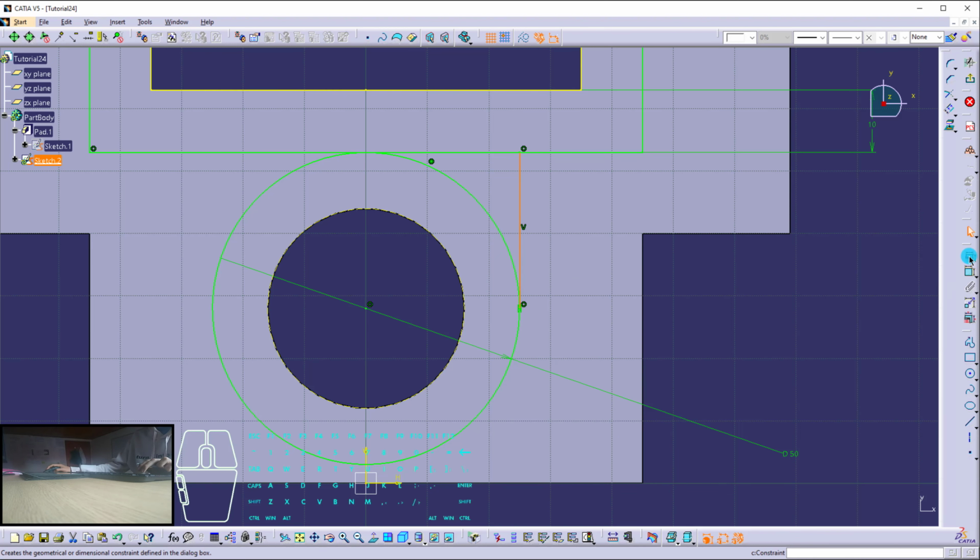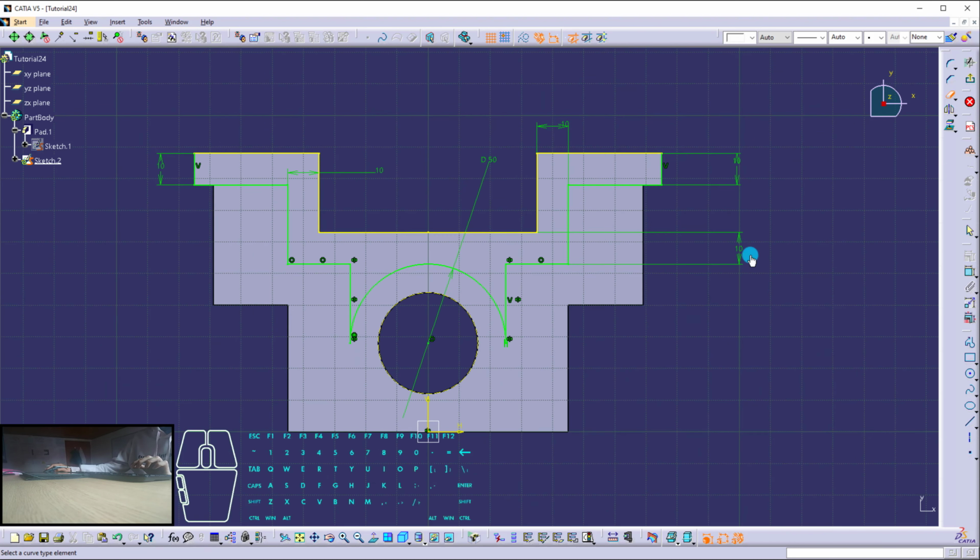Click on it. I'm going to create once again a mirror with respect of this axis. Right there we have it. And I should get rid of every single line that I do not need. So I'm going to use the quick trim, double click. This line I do need, this I don't, this I don't, and this I don't. Right there we have it.